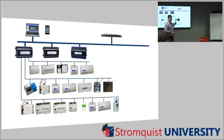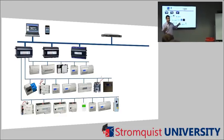N2 is a good example because N2 is the Johnson Controls proprietary communication protocol. So you may have in your building part of it N2 where it's proprietary, and then you may have a system like BACnet with its own type, maybe it's a Jace, okay?